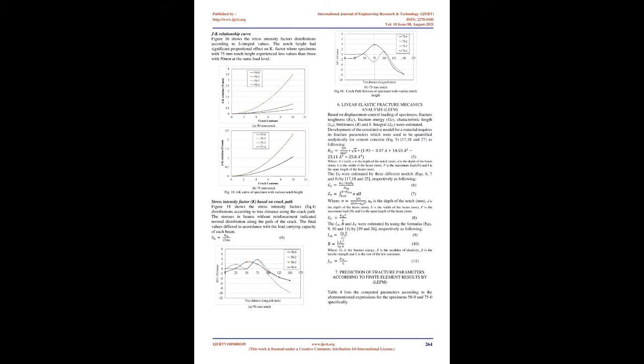Figure 14 shows the results in the finite element and experimental model. The differences between experimental and FE in terms of concrete deformations were considered due to both the limitations of concrete to deform with cracks and the crushing technique in Abaqus. In general, the experimental and FE responses have the same trend.